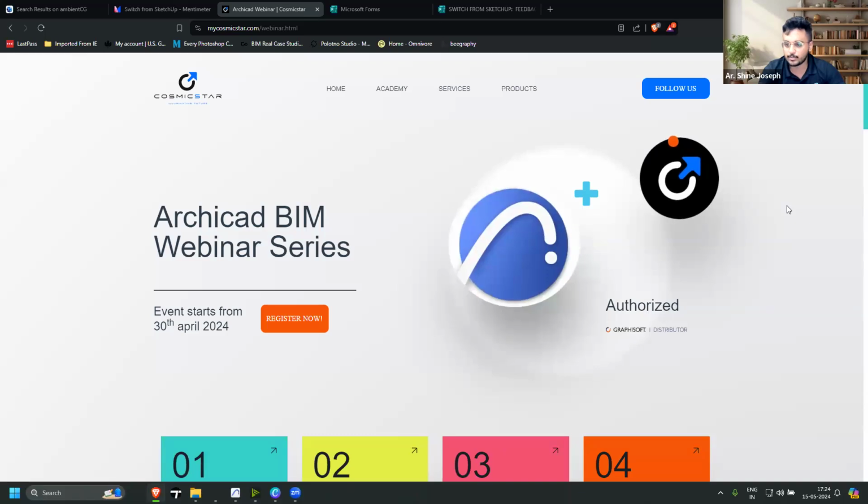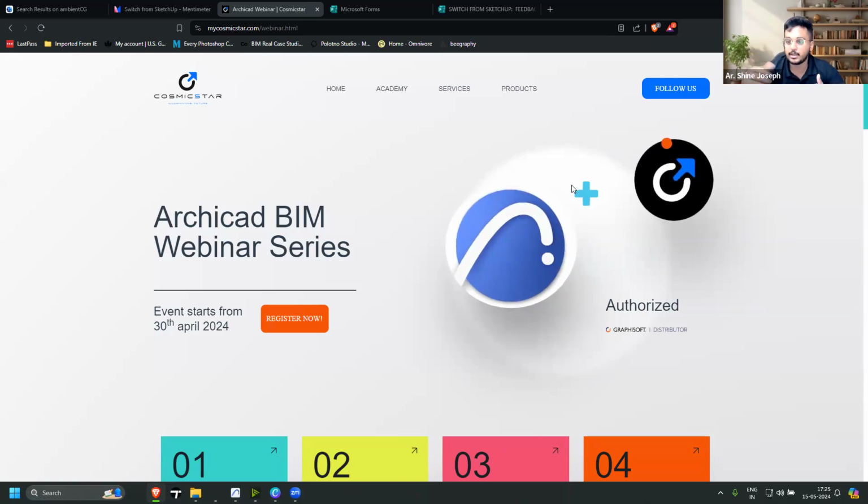There is one more question from Pooja: can changing shapes, like parametric forms, be created? I did not get the question. So I'm assuming your question is about controlling the shape. There is actually a different way of doing it. For example, there is a tool called the Shell tool, which lets you have two different profiles and combine them. Whenever you change one of the profiles, the shape changes.